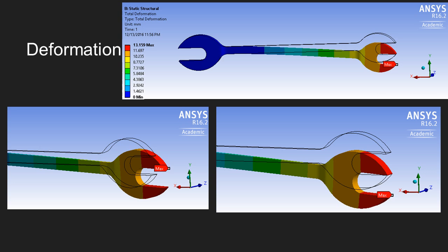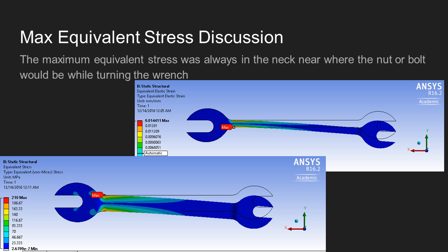This wrench was analyzed to see how much material could be taken off to reduce the cost of production, but it failed. The wrench with the slightly less reduced cross-section had a total deformation of about 3 millimeters under maximum loading, which is equal to about 0.1 inches. This wrench only failed at the maximum loading, so it could be used in some situations and not break. The rest of the wrenches generally had a deformation under 1 millimeter, which would be almost negligible.